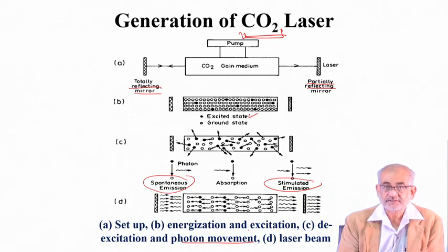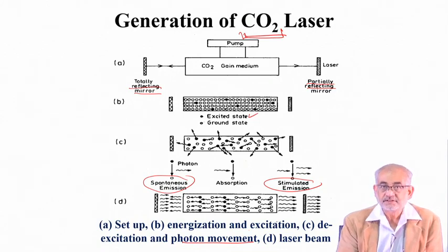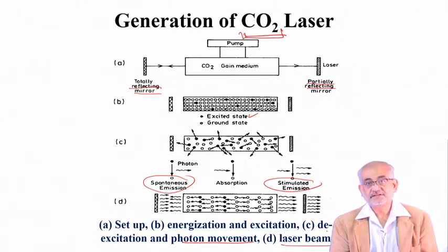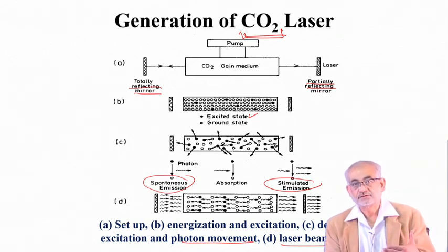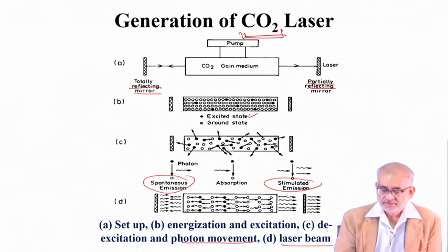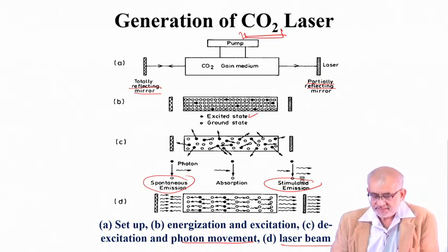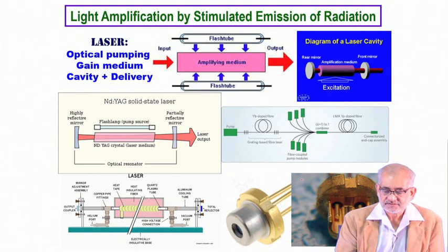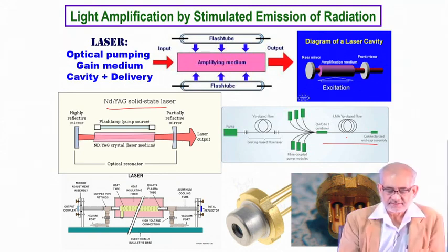And once they can make constructive interference, or they are coherent with each other, then there'll be emission of laser initially, and the total intensity of the laser will depend upon the population that will undergo excitation, subsequently inversion, and also which will be able to maintain the coherence. So this is the process which is by and large true for all kinds of laser, be it CO2 laser or solid state Nd-YAG laser or diode laser or say fiber laser. This is one of the most common and the most widely used high power laser variety.